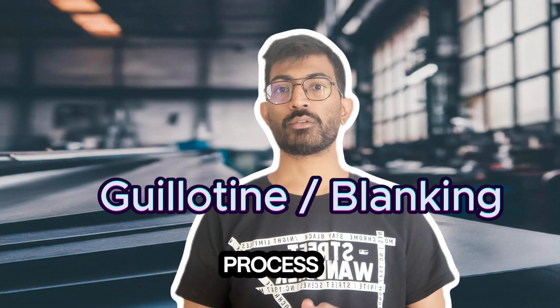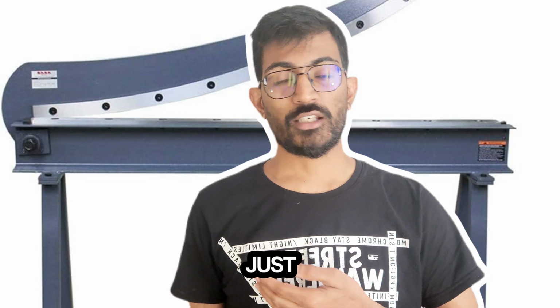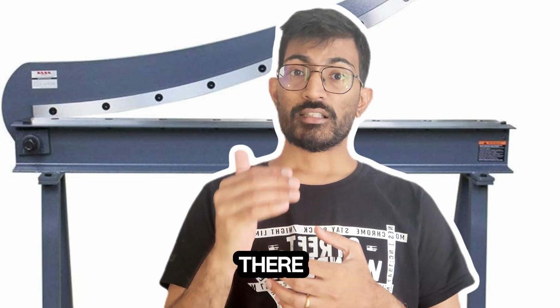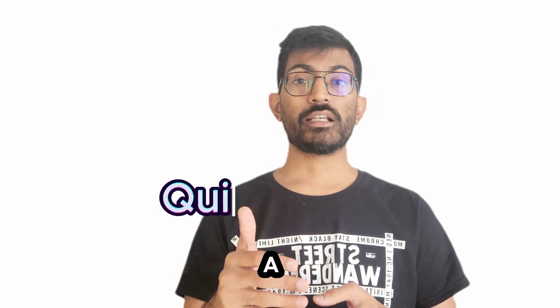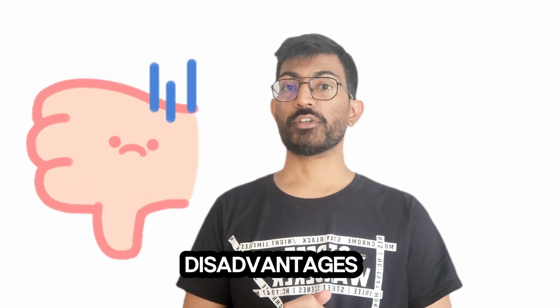Blanking is a process where you have a blade coming from the top and we cut it just like a vegetable. There are some good advantages of this method. Number 1 is you require less skilled labor. Number 2, if your product can work with straight line cuts, it is a really quick and really efficient way to get things faster than laser cutters. Now, what are the disadvantages of this method?